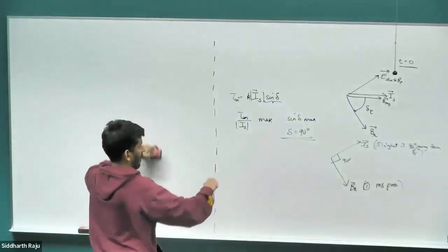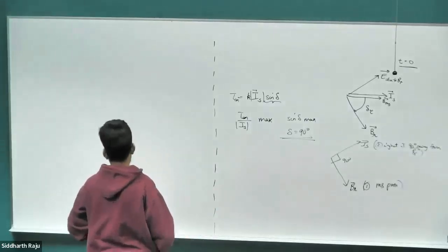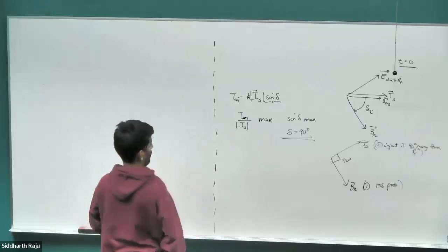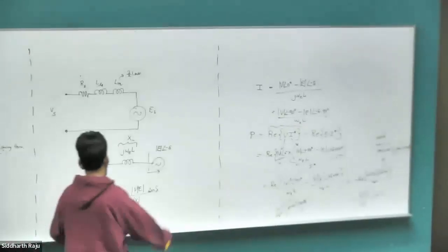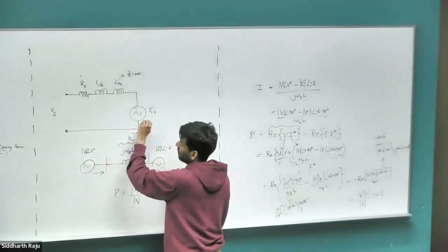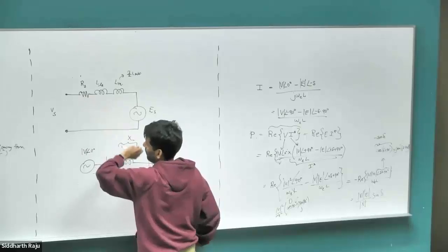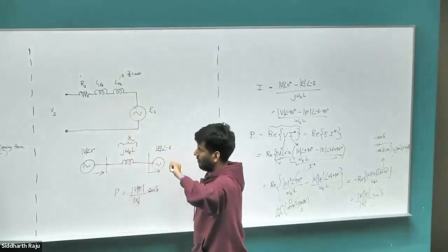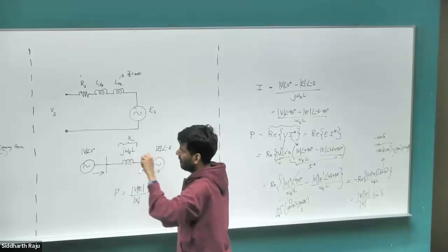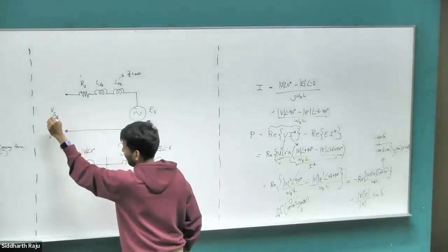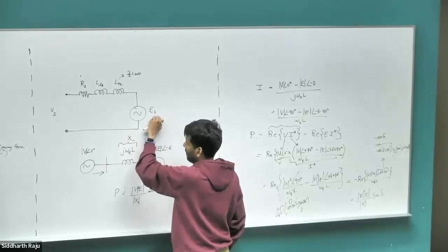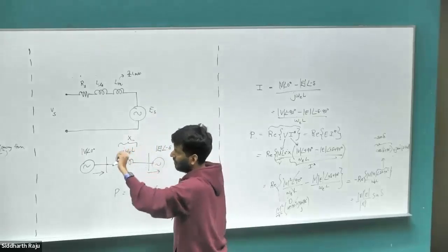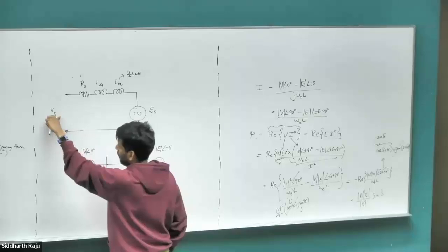Now we can extend the same thing to our permanent magnet motor as well. If you look at the equivalent circuit that we have there, this and this have exactly the same form, except if you ignore this resistance term. If you assume the resistance is small enough, then we have some terminal grid voltage which is fixed. We have some back EMF coming from the motor, which at steady state is going to be fixed because the frequency of this grid voltage is fixed.